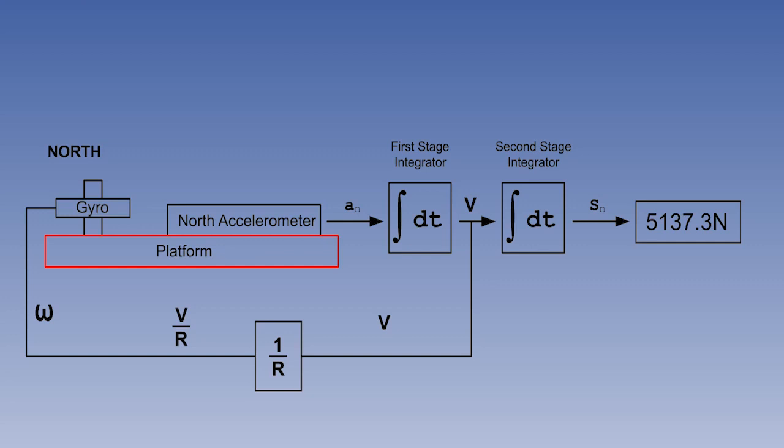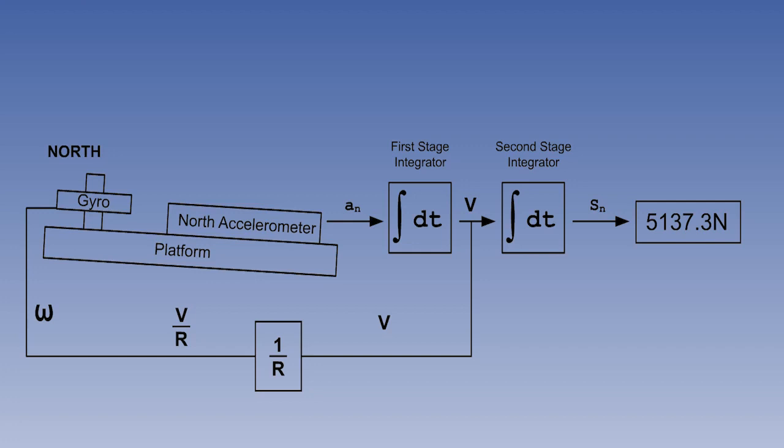Firstly, the platform may not be perfectly level. Platform tilt can also be known as initial leveling misalignment. The leveling process during alignment is very accurate. Ideally, it should be within about 6 seconds of arc. This is 1/600th of a degree. Nevertheless, it is a compromise with the requirement for a reasonably short alignment time. On completion of the alignment, the platform may not be perfectly level.